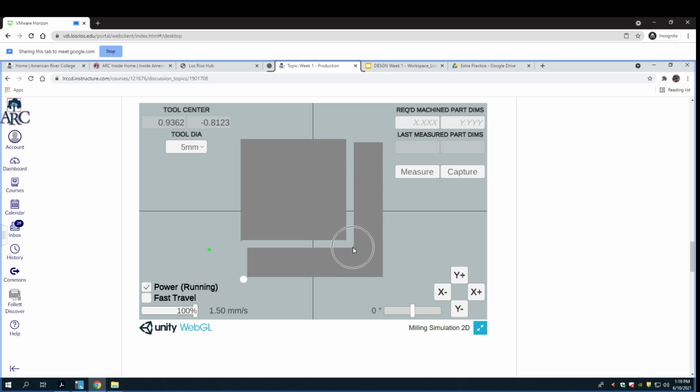The radius also has to do with the strength of the object in what's called fatigue. So let's pretend that the engineering intent was that there would be a weld along the bottom and that this is a bracket that something's going to push, and it will cycle. Force.